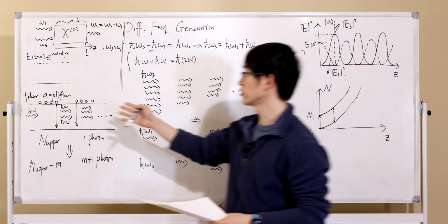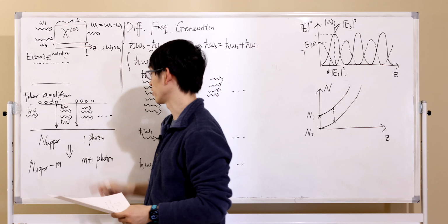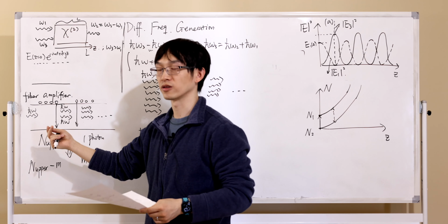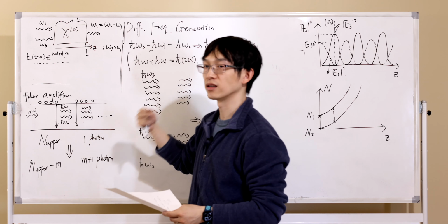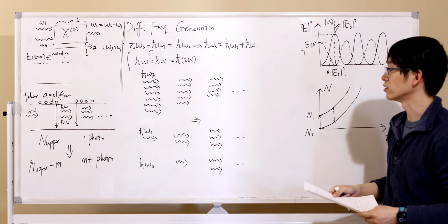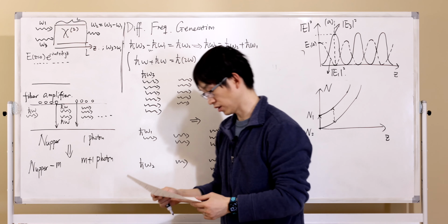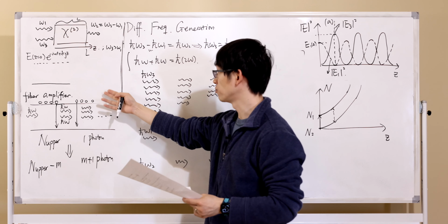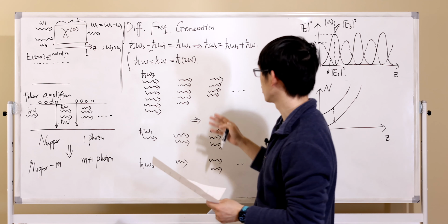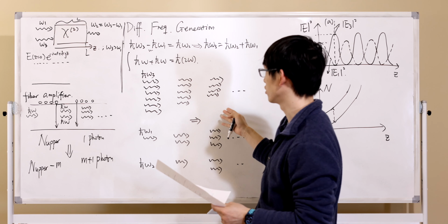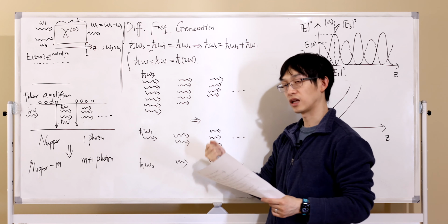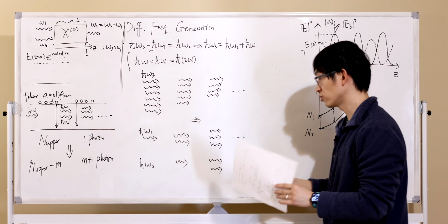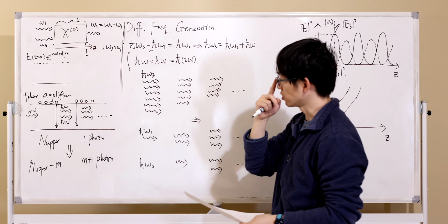For the conventional fiber amplifier, what's being amplified is the number of photons. The frequency doesn't change. That's usually the meaning of amplifier in optics. The difference between a conventional amplifier and a parametric amplifier is that after amplification, the state of the material doesn't change. And why is that important? That's important for a few reasons.